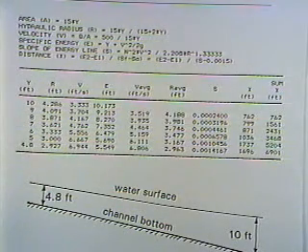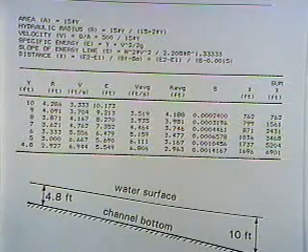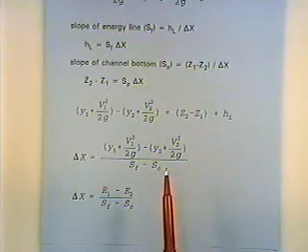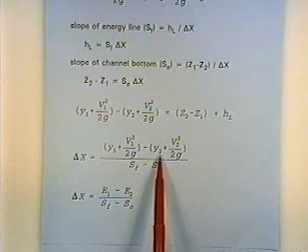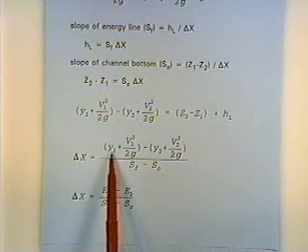What we'll actually compute is the location, the delta x. If we go back to our basic equation, we'll just be plugging into that equation over and over again. I'm going to flip back to it a few notes back. The direct step method for gradually varied water surface profiles: we're computing the delta x. At some place the depth is 10 feet. We'll plug in 10 feet here, and 9 feet there.